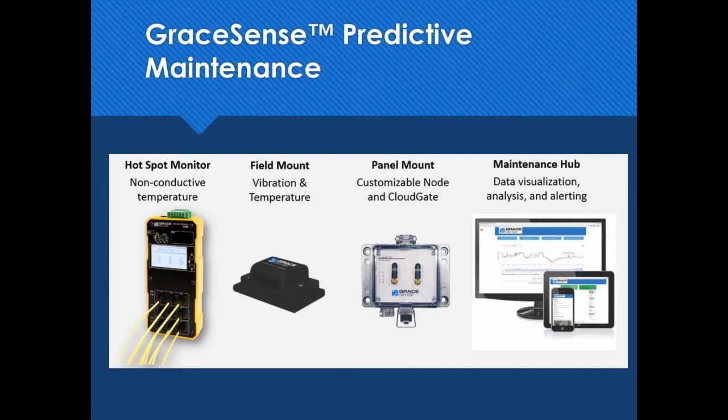The next one you see on screen is a vibration sensor that could be applied more on your rotating machinery, for example motors, pumps, generators, or compressors, so that you monitor the vibration data and take these parameters to perform or plan for the maintenance activities accordingly.